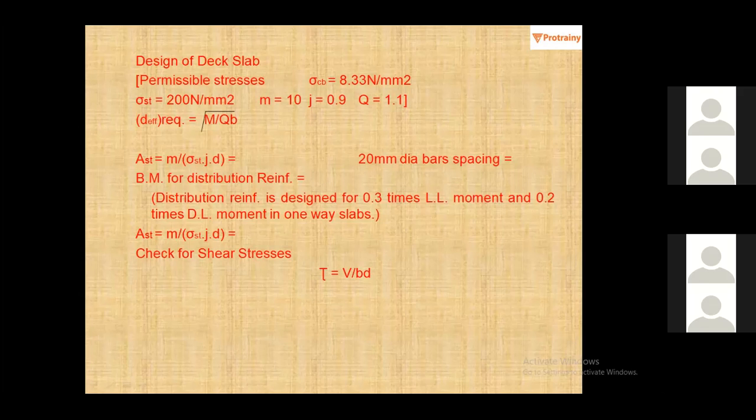So this is the effective depth which is required, and we are providing 450 mm. So our assumption is fine. We can move on now.